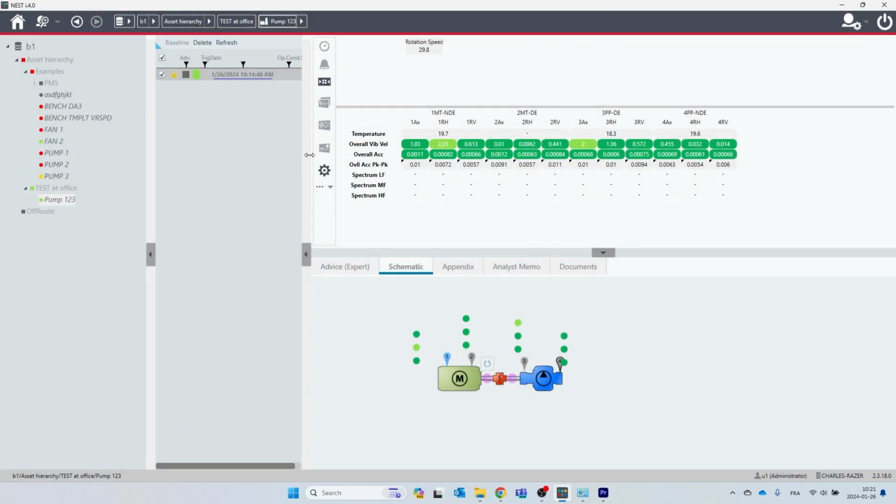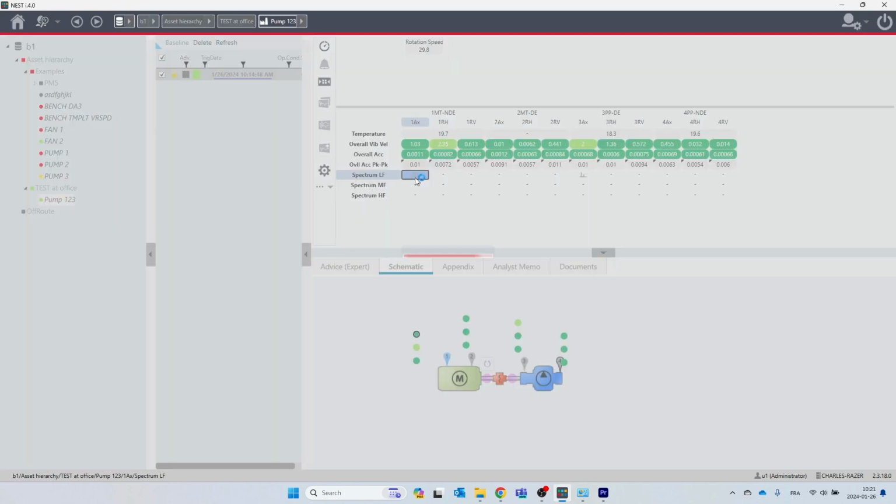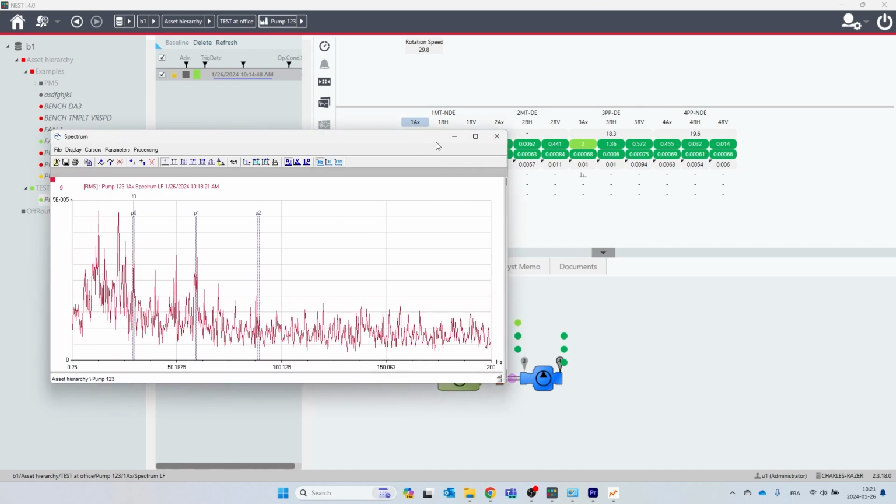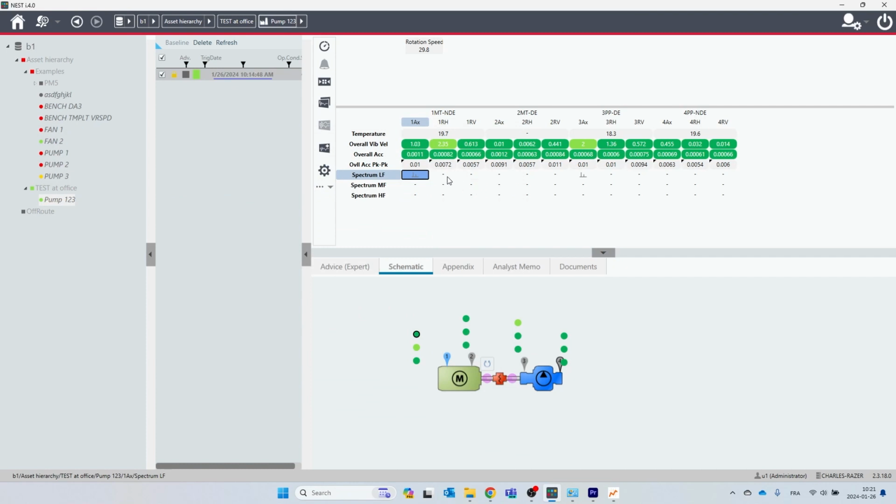Okay, so after a few minutes of waiting and refreshing, 6 minutes, I got some values. Here you can see that it downloaded all the overall values and the temperature of my sensor. It already has a few spectra that I can check and analyze. If you leave it a little bit more time, it will keep downloading all the signals and everything, and it will periodically take its readings. So that's how you connect the Eagle system and start an acquisition with the Eagle system.